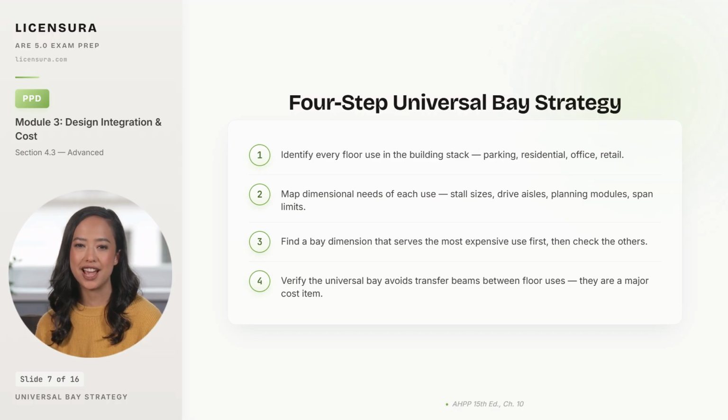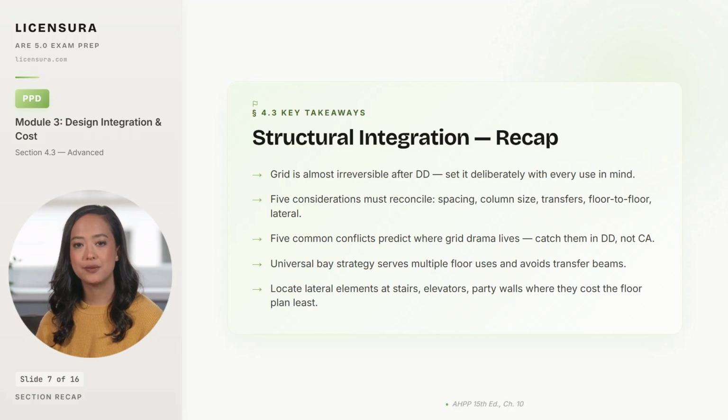5 takeaways from the structural integration framework. The grid is almost irreversible after DD because foundations, lateral system, MEP risers, and the facade rhythm all commit to it, so set it deliberately, with parking and occupancy and facade module all considered together.